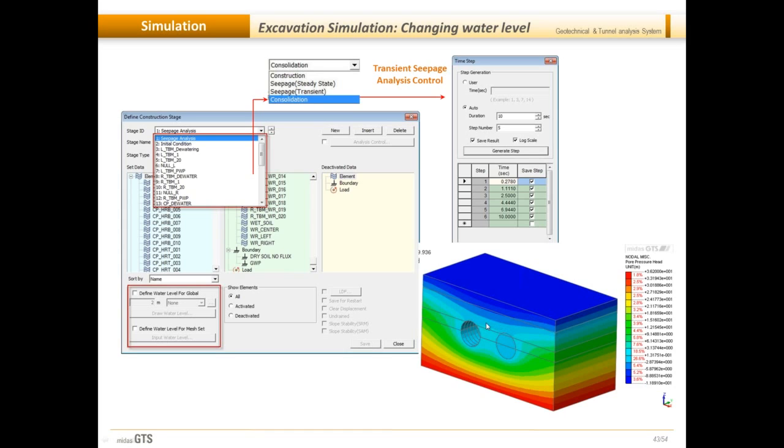And this deformation will continue to occur until the pore water pressure equilibrates and appreciates the presence of the tunnel interface there. So till the time it stabilizes, you will continue to get deformations and thus additional forces on the tunnel. And recently there have been a couple of cases where tunnels have collapsed or have shown increased deformations that have rendered them unsafe for use until further repair because of these effects.